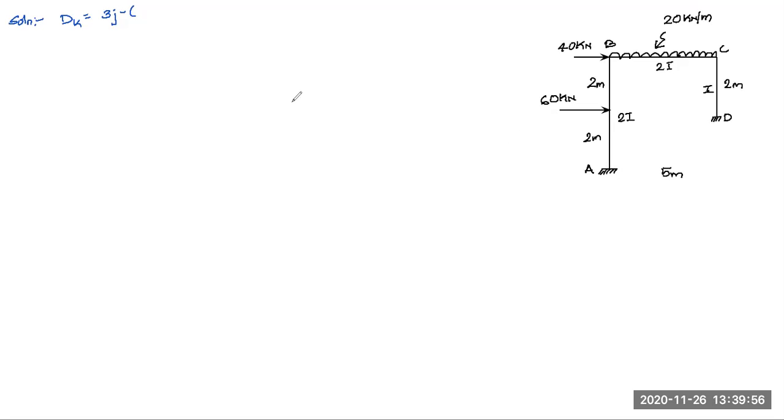Whatever number of reactions there are, those are the restraints applied on the displacement. So you can write that as 3j minus r plus m, the number of inextensible members. If the members are axially rigid, we consider them inextensible members.